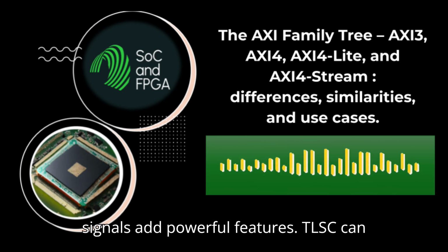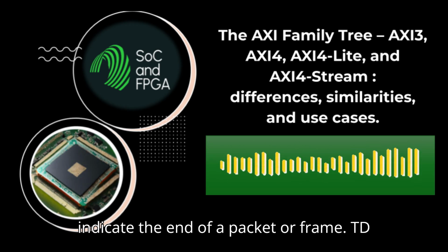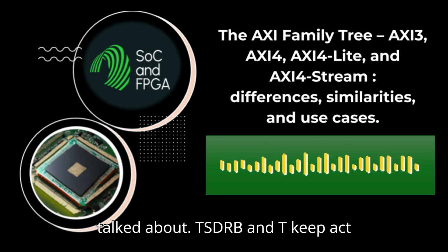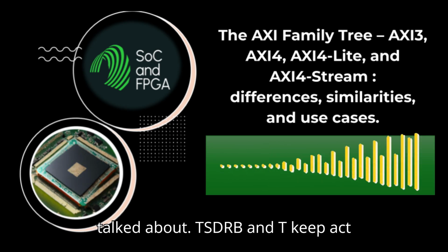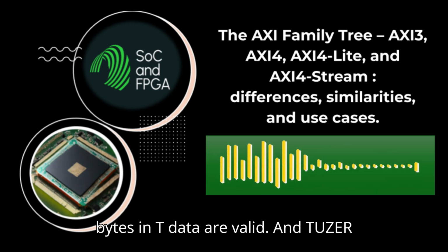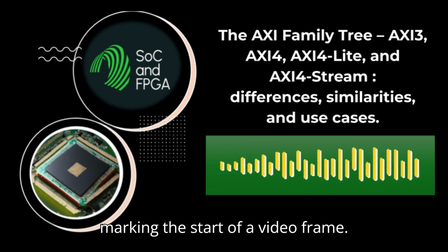Yes, optional signals add powerful features. TLAST can indicate the end of a packet or frame. TID and TDEST can provide stream or destination IDs for that multiplexing we talked about. TSTRB and TKEEP act as byte qualifiers, indicating which bytes in TDATA are valid. And TUSER provides a channel for application-specific sideband data, like maybe marking the start of a video frame.